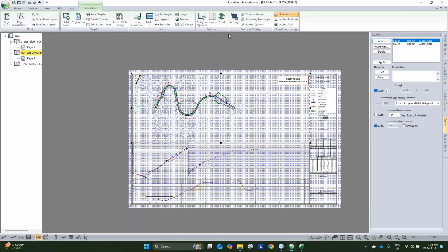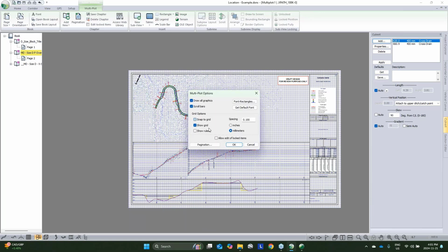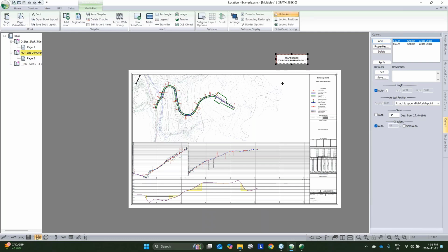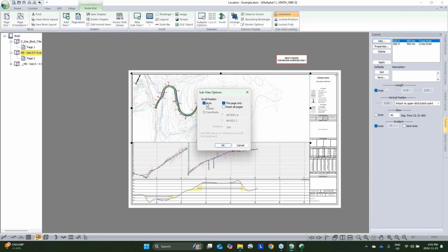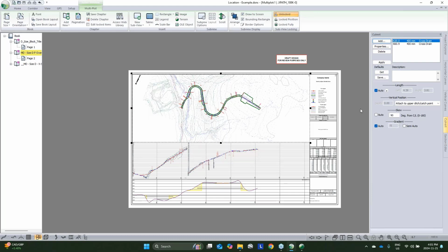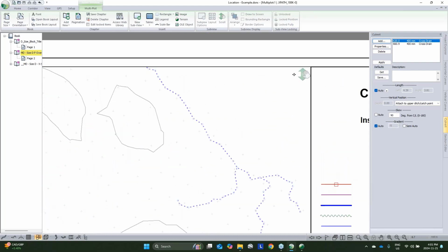And just on that scroll piece, I know, Matt, you've got your grid displayed here, but there is an icon. So if you are reusing a layout on another project and you're wondering why it's not in the right position, there is an icon if it has scroll enabled to be anything but auto to show that it's manually scrolled. It's in the little corner. It just gives you a visual clue to know that you've got something that is set to something not auto so that you can remove it in the future. So if it comes in a little bit wacky, check for that scroll piece.